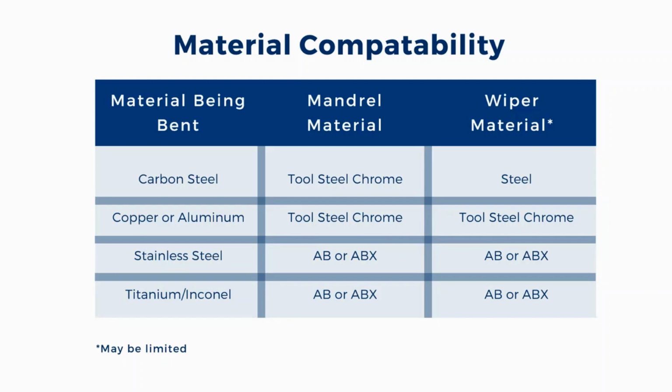And hard tubes need softer materials, i.e. stainless steel, titanium, and Inconel go with aluminum bronze mandrels. The 2 forms of bronze shown here are AB18, which is the industry standard, and ABX, which is a harder, more durable option offered by OMNI-X for about 25% more cost and provides 2 times the life.